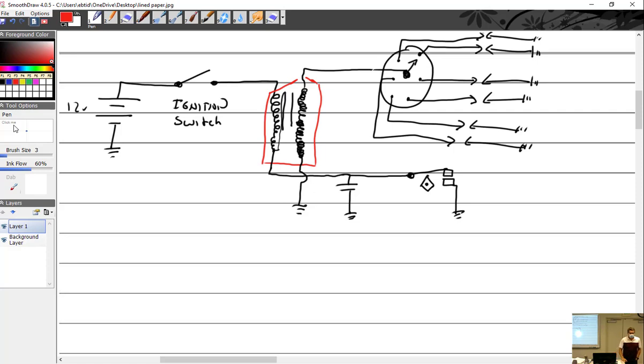All right, you got that all drawn up on there? Let's talk about what we've got going on here. First thing, and I'll write notes for you afterwards, is a battery, right? This is the Kettering or battery ignition system. This exact style of system was used on older cars, not electronic ignition.